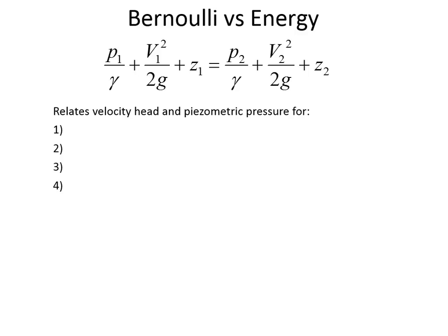And we know that those conditions are never met, because a fluid that has no viscosity doesn't exist, but those fluids that have very, very low viscosity, like gases, are compressible. And what we're trying to have is a fluid that's incompressible. Maybe water comes close, but then water has viscosity. And so there really is no perfect fluid that will apply entirely with Bernoulli's. And so when can we apply Bernoulli's equation with confidence? There are some places that we can apply Bernoulli's and it works pretty well, and others when we really shouldn't be applying it. From a practical standpoint, not from the pure standpoint of what these 4 assumptions were.